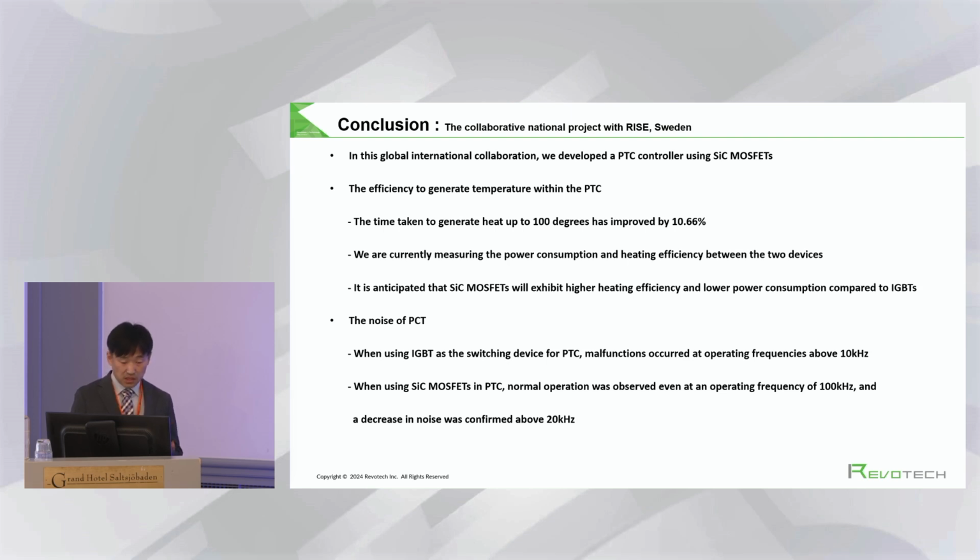Furthermore, when employing SiC MOSFETs in the PTC system, we observed normal operation even at an operating frequency of 100 kHz. Additionally, we confirmed a decrease in noise levels above 20 kHz, showcasing the effectiveness of SiC MOSFETs in enhancing performance and reducing noise in high-frequency operations.